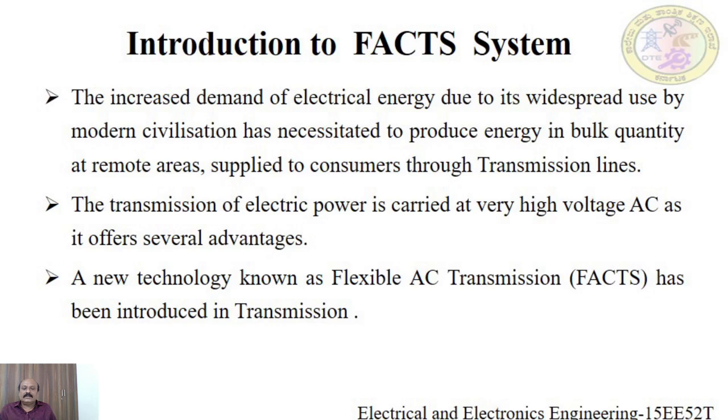So the reactive power loss may be the sum of the reactive power generated due to the line capacitance or consumed due to inductive reactance. During light load conditions, the inductive reactance absorption will be less when compared to the reactive power generated.